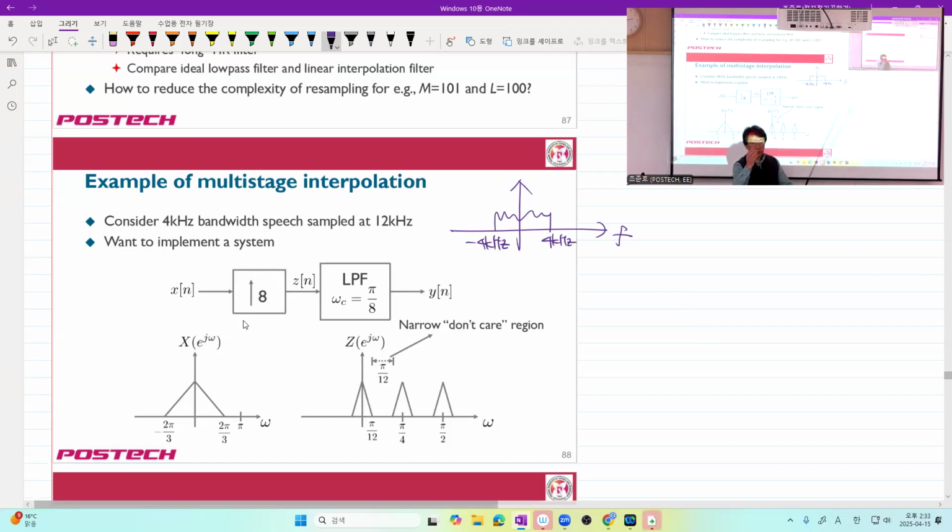Long ago, the public telephone network had a filter that cuts the signal at around 3K. So what happens? Your consonants, with high frequency, are a little bit suppressed or cut out, so it was very difficult to understand. And this was not the only problem of the public telephone network, but also happened in the communication between the control tower of the airport and airplanes, and even the command center of the Air Force and fighter jets.